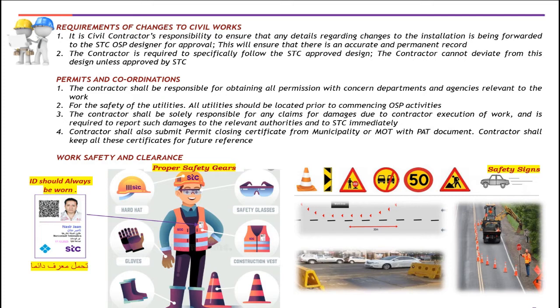Okay? So a detailed hazards and safety assessment management plan form should be filled by the field contractor prior to commencement of any work. As a matter of courtesy, the contractor shall send a written notification letter to the owners of the affected premises and buildings prior to commencing any works. Okay, so local authority directions shall be followed if so required. Pedestrian access shall be provided at 100-meter intervals, and crossroads shall have decking provided to permit the passage of vehicles.